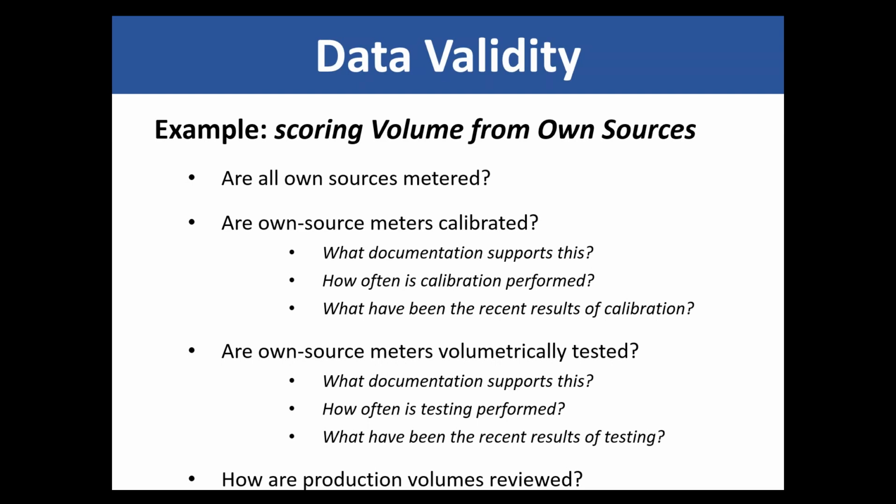And those volumes, this one summary volume that I have here, the underlying data from my SCADA comes in at a much higher frequency than just one annual number. Who is reviewing that? Have we had any lightning strikes happening where our SCADA was down for a couple of hours? Did someone fill in the gaps there, or do we have zeros? And when we pull down the cell and summarize everything, we're summarizing also the zeros where actually we still continued producing water. So those are the things you want to look at and ask questions around.